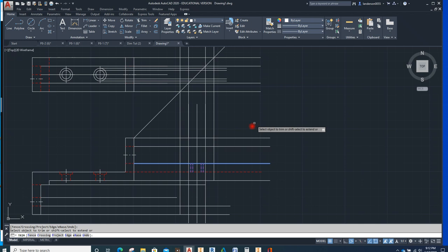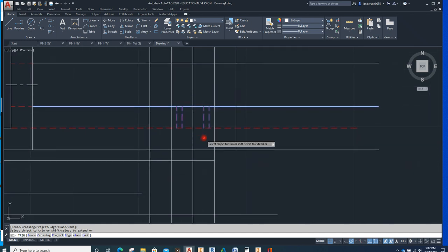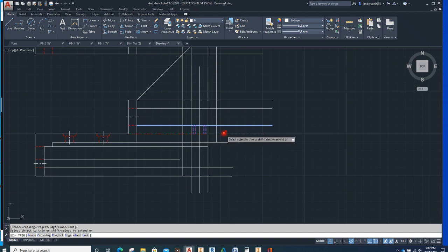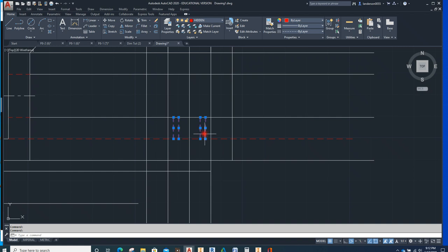Okay. And these guys need to be down a little further, because that was supposed to be my trim line, which is easy. All I gotta do is click those, mirror, use that line right there, erase source objects, there we go. And then, in this case, I can bring that down 0.12, and I've already got that.